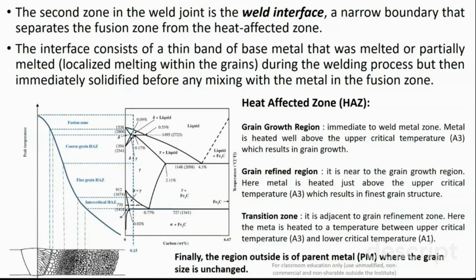All these microstructural transformations occur due to recovery, in which the rearrangement of the dislocations produces strain-free regions, and those strain-free regions inside the grain give a site for nucleation. If you continue to heat the grains, there will be recrystallization of new grains, and the new grains will start to consume the old grains.